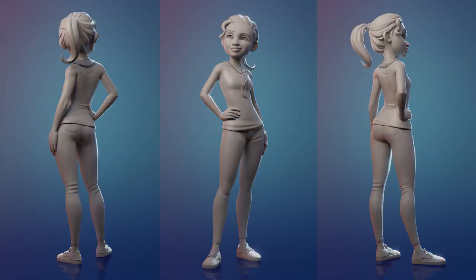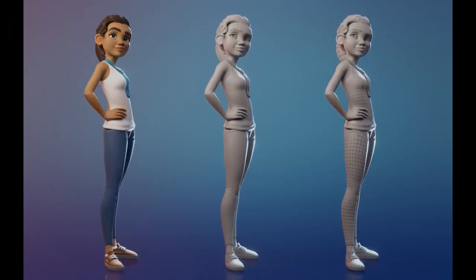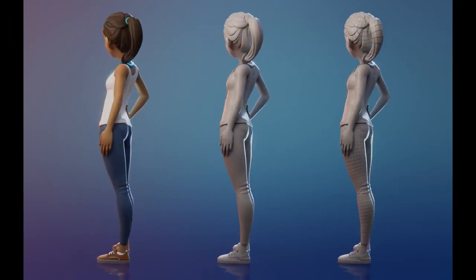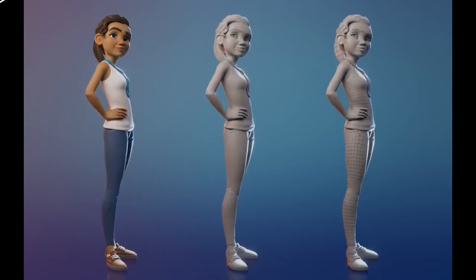A so-called clay render is also good to show off the model itself, where it's rendered colorless in diffuse gray with only the bump and normal information at most from the materials. Add wireframes on top as well to show off the clean topology you created. Render those also as turntables and you have a complete character for production that you can show off.